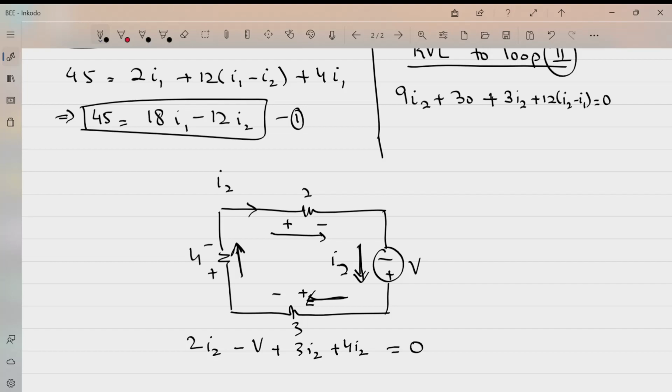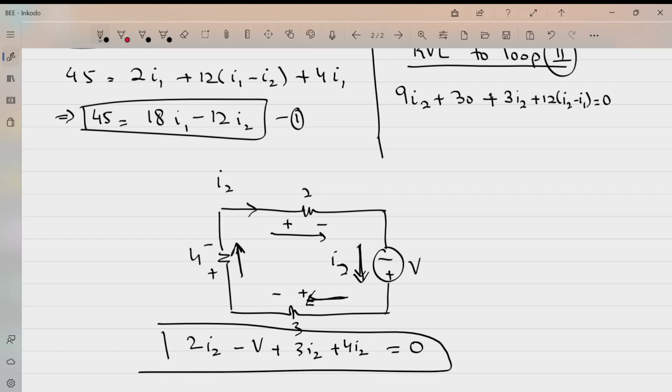So you should always keep, you can start always by doing this thing, that you add all the voltage and equate those terms to zero, rather than saying that this particular voltage is equal to all these voltage drops. Okay, you can make a habit of using this type of equation. Equate, subtract, add all these equations depending upon direction of current and equate them to zero.